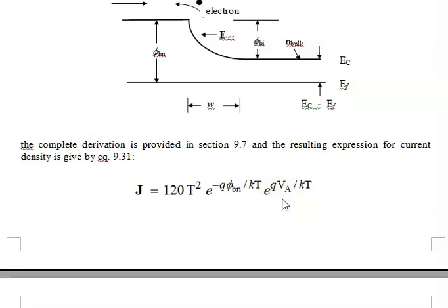We'll see why, because drift current tends to be fast, diffusion current tends to be a little bit slower, so Schottky barriers are good at high frequencies. However, there's always a downside. Nothing's perfect in life. The problem in Schottky barriers is this guy doesn't change, so we get relatively high reverse currents, whereas in PN junctions, in reverse bias, I can make the barriers extremely large, so the currents in reverse bias for PN junctions are smaller than they are for Schottky barriers.